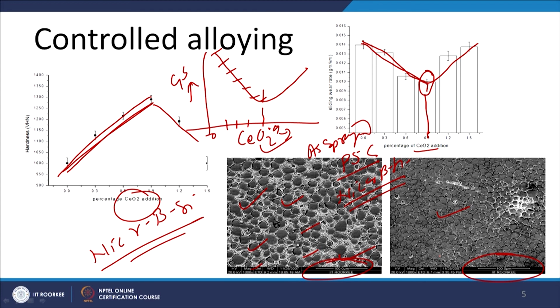Now, I will summarize this presentation. In this presentation, I have talked about the 3 approaches which can be used for enhancing the performance of flame spray coatings. These were compaction, which primarily eliminates the pores and breaks the inclusions if they are there, and in case of remelting also helps to refine the grain structure.